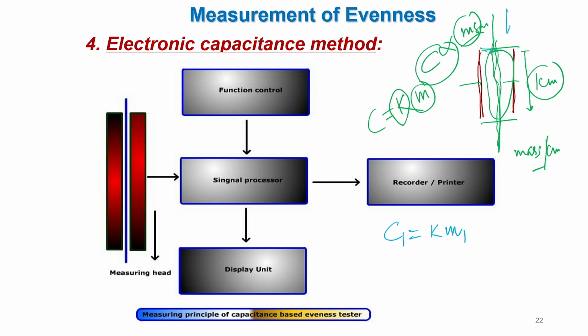Now, in the next section the material is moving, the sliver or yarn is moving at a known delivery speed V. Now, after a certain time t, this portion will come out and a new portion will enter here, and the time of movement of 1 centimeter is dependent on the delivery speed. So, what is the time lapse?